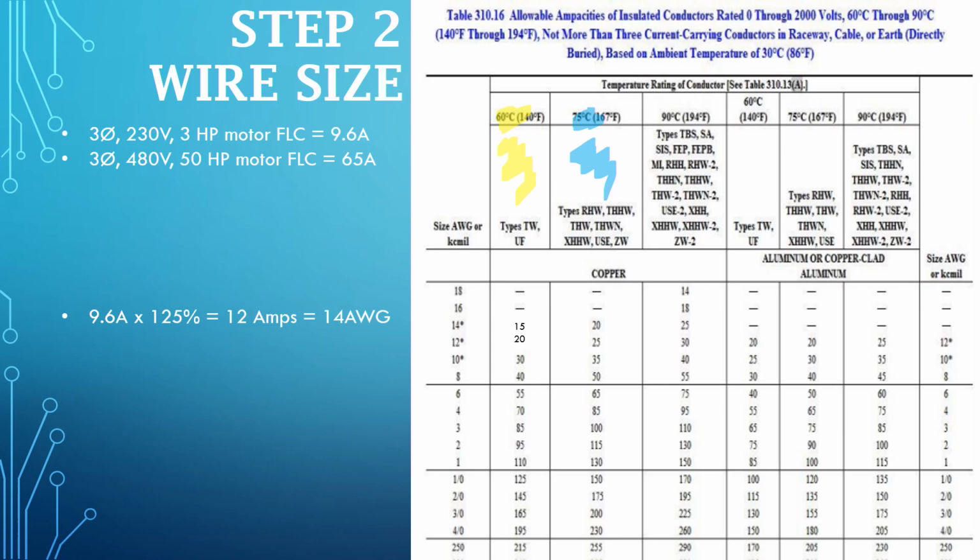Now, if it's more than 100 amps, those devices are required to have at least 75-degree terminals, so we can use the 75-degree column, because anything that's over 100 amps, all the terminations have to be able to handle the 75-degree conditions. So when looking at our 12 amps from our first problem here, I can see that 14 AWG will hold 15 amps.